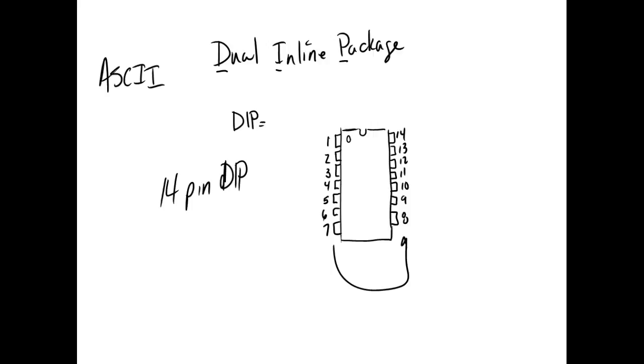So what you're looking at is a 14-pin DIP. There's a picture of it on page 51. The spacing is critical, and we'll show y'all some 24-pin DIPs. They got bigger, all the way up to 64 pins. The biggest thing I ever seen in a DIP package was a Motorola processor, 68. What was that? But it was a 64-pin DIP.